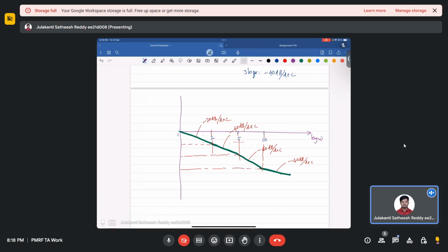The Nyquist plot is useful if the system has some delays. The root locus can also be used for determining these things. Okay. So the root locus will give you the exact location of the poles, the trajectory of the poles. The Nyquist plot will give you how the system function behaves when we have delays and so on. Even though you can do it for any system, whether minimum phase or non-minimum phase, you can do the Nyquist plot also. But to understand whether the system is a first order or second order system in the frequency region, you can get the best out of the Bode plot.